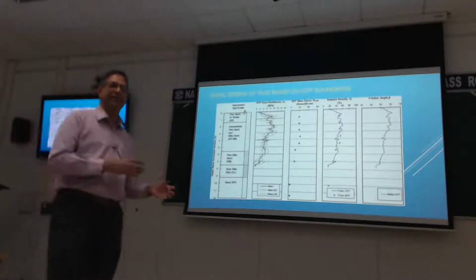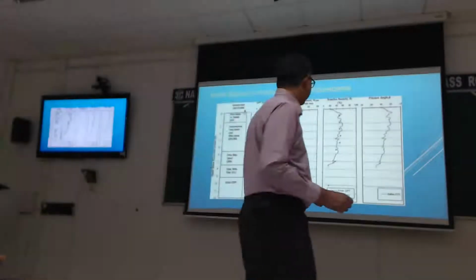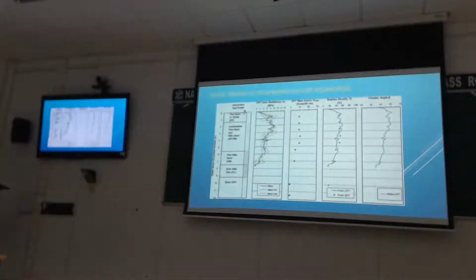So if he says something about them, he probably thought about it quite carefully. The basic idea of designing piles based on CPT is quite sound, philosophically. Why? After all, when you're pushing a CPT into the ground, it is like a mini pile. So if you're measuring the resistance on the mini pile, all you then need to work out is how to scale that to a bigger pile. That's all we need to do. So it makes sense inherently that we use CPT.